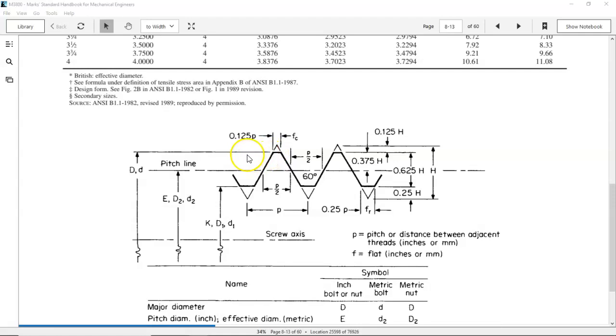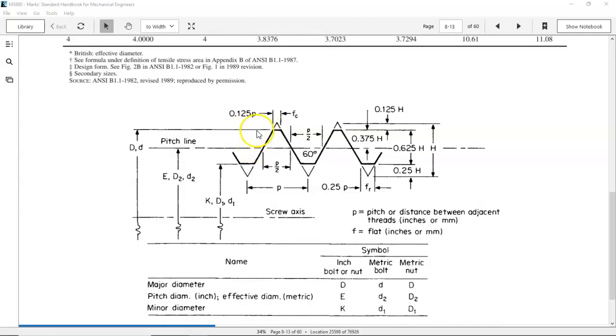And looking at this, it's kind of hard to decipher what's going on with all of this geometry, but if we look at this as a full helical revolve, the major diameter is to the outside, the minor diameter to the inside. Pitch is basically where the internal and the external, that pitch line is where they're going to meet on engagement and have the clearance.